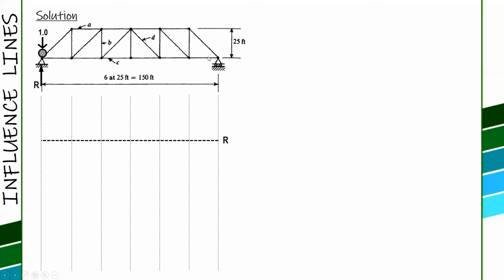First, place the unit load at the left support and then compute for R using statics. Sum up moments at the right support, and then move the unit load to the next joint at the bottom chord, and use statics again. The RA is equal to 5 over 6, and then RA is 4 over 6 or 2 thirds, and then at the center by symmetry, the reactions at the two supports are equal.